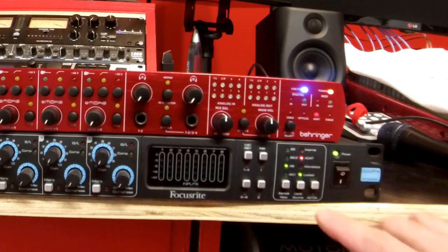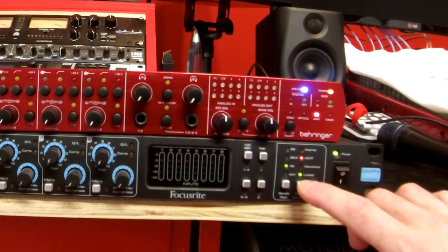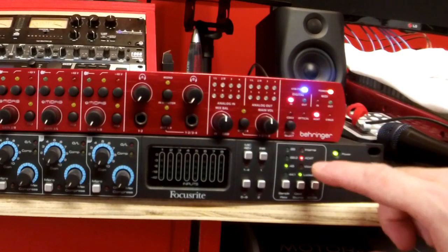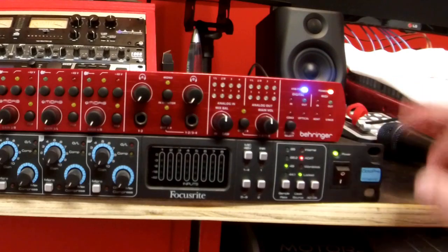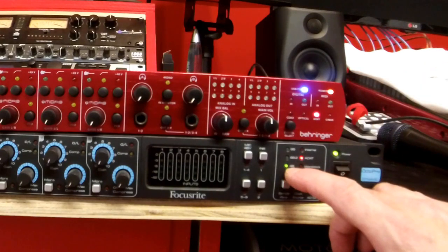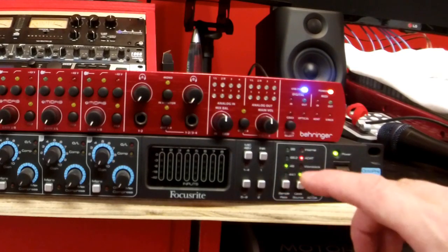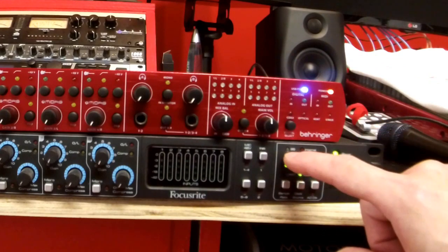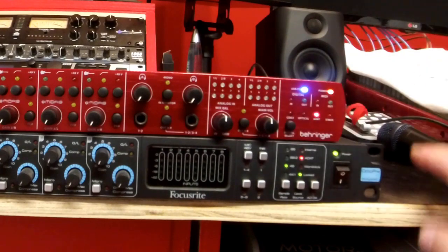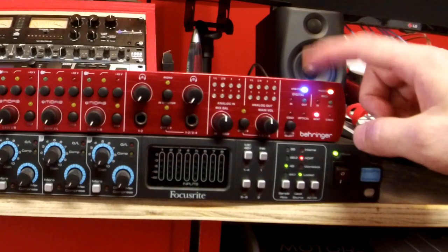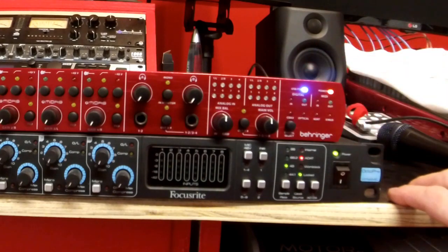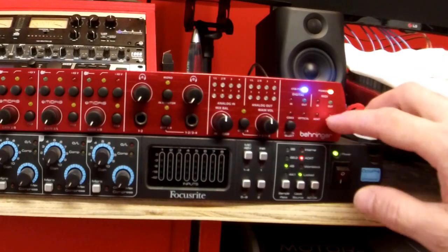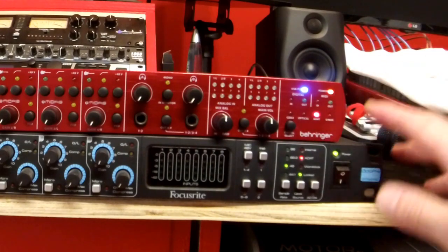USB connected, and here at the bottom we can actually see the green LED. It says locked. That means we now have the two units talking to each other and locked. I also have the sample rate selected 48, which is the maximum for the Behringer unit, even though the Focusrite can go all the way up to 96 using two sets of optical cables, but the FCA1616 only supports up to 48. So that's the highest rate I've selected, and it's locked. Even though it's flashing, that's only because it's not talking to the PC at the moment.